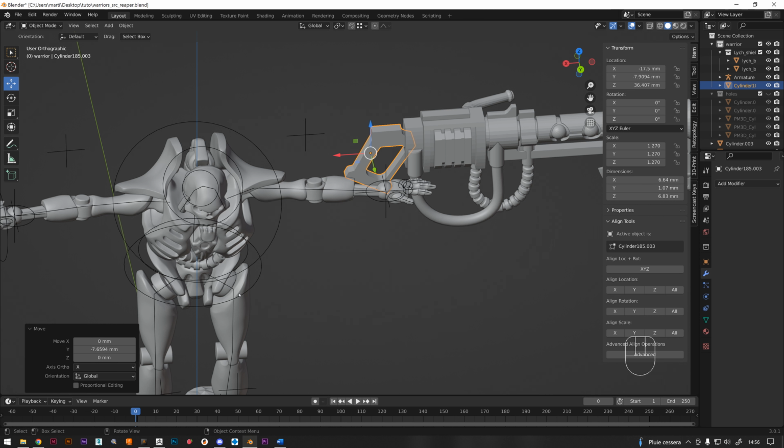We can do it with 1 dimension, along a line, or with 2 dimensions, along a plane, but not with 3 dimensions. This has its advantage. For example here, if I want to adjust the position of this element keeping it in the barrel's axis, well, in this case, we only need one axis, the X. Because what we absolutely don't want is moving the object along other axes, as this would cause the object to come off the axis of the barrel.